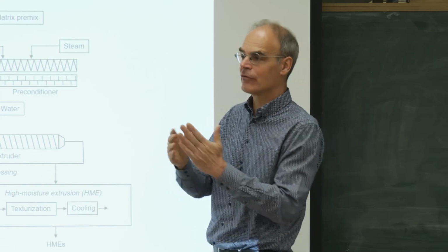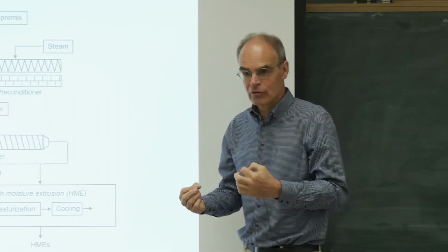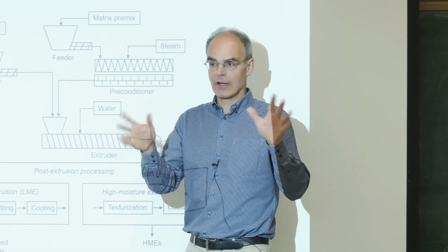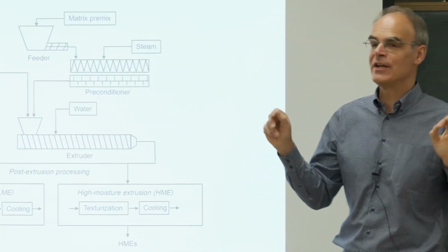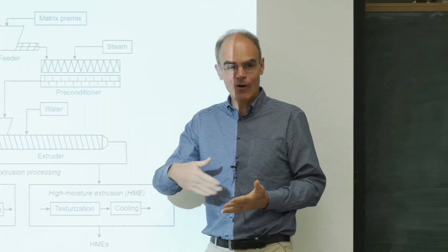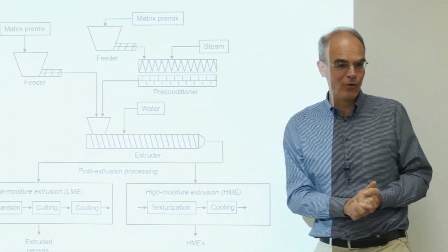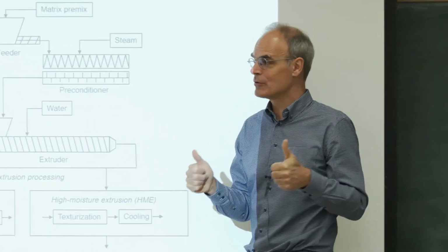So we have that active transport of material in that extruder barrel, which is pretty low viscosity. It's about, at that temperature, let's say the consistency of a thickish peanut butter or something like that. Peanut butter doesn't really transport very well. You need to have something to really help that move along in that barrel. So very good, single screw, twin screw extruder, yes?